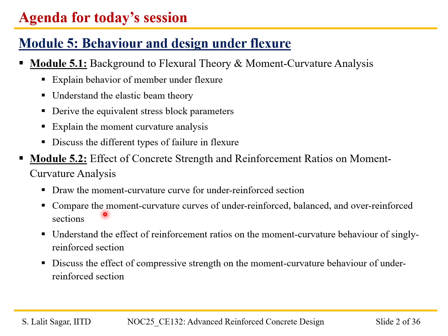And then we understood the effect of reinforcement ratios on the moment curvature behavior. So that is when we perform the moment curvature analysis and plot the moment curvature diagram, how the shape of the plot varies depending on the reinforcement ratio. That is what we looked at.